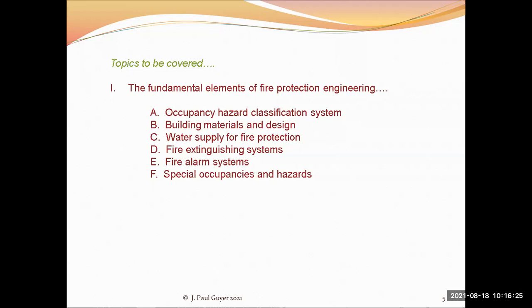A reason, incidentally, that you see this in industrial parks, warehouse parks, things like that, is that warehouses are a particularly hazardous type of building from a fire protection standpoint. You might think that's a little odd, because in a typical warehouse you don't have a lot of people in it, and you don't have them doing much more than moving products around and shipping them out. But the reason they are particularly hazardous is that all of that stuff stored in a warehouse is fuel for a fire. So that's why warehouses are particularly threatening, if you will, from a fire standpoint.